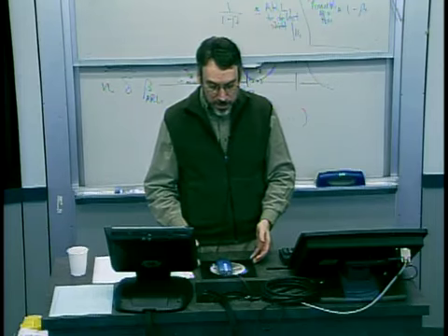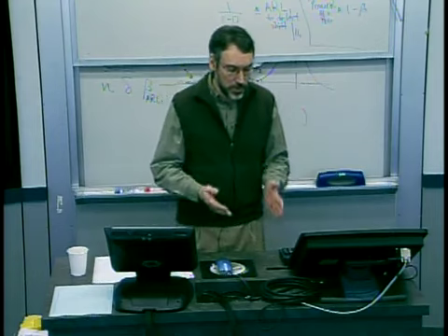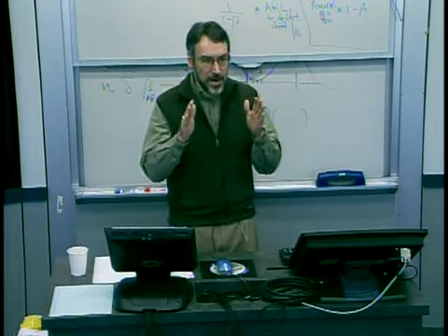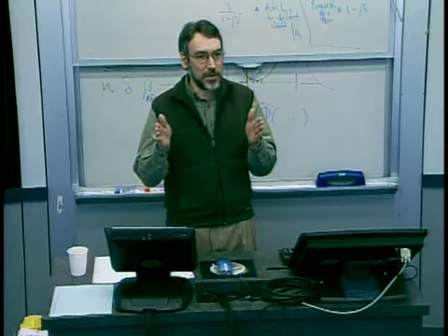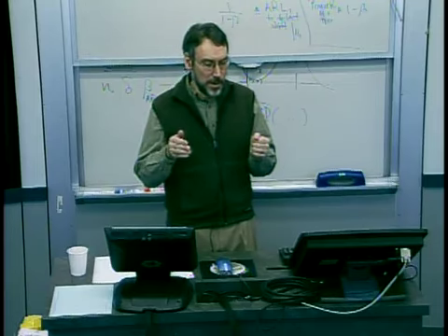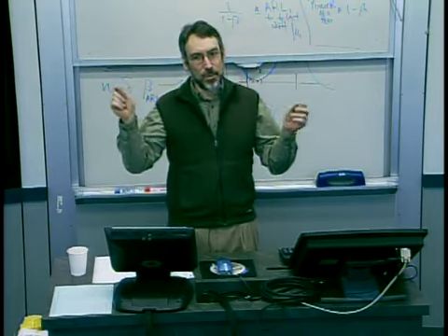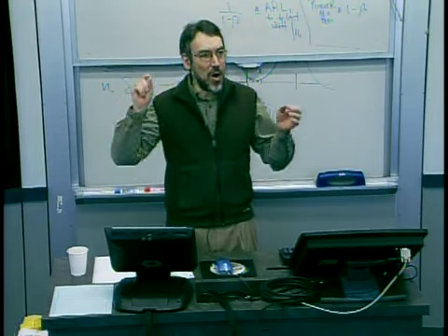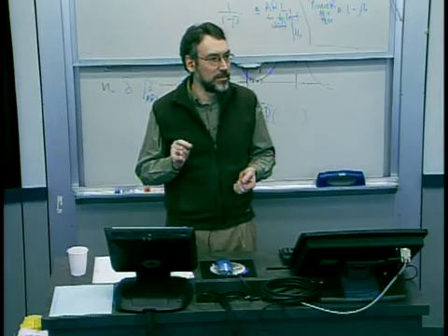Right. So I can't tell. Yeah. This is a fundamental, important point about how control charting works, which goes back to the idea that if nothing changes, you do have false alarms, and if something changes, you've got a real alarm. All you've got on the control chart is a point that's lying outside of your normal bounds. All by itself, from the control chart, you can't tell.